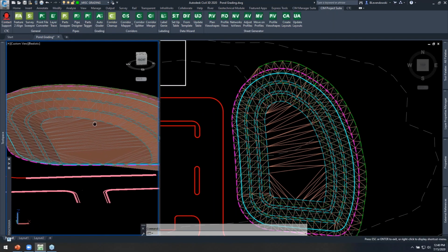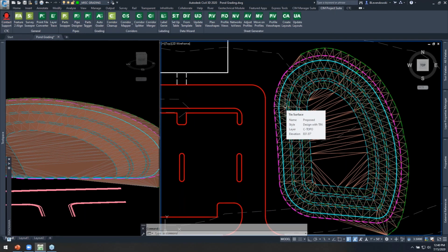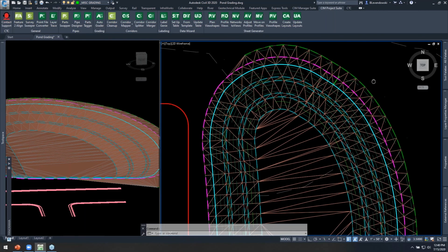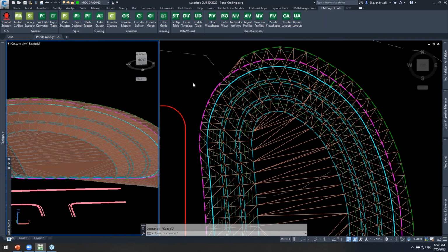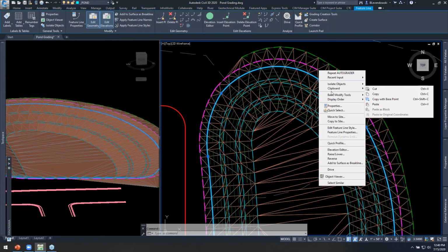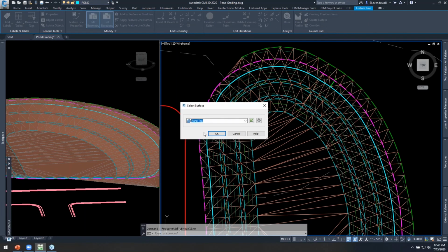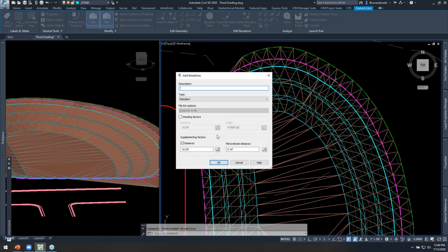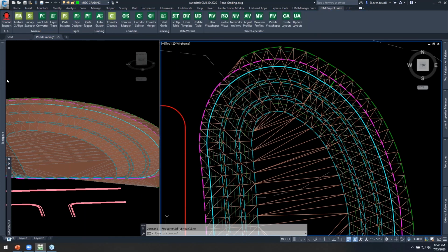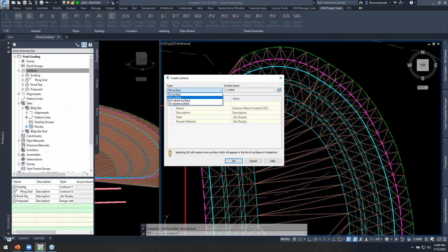What your pond design looks like, right, it varies, it depends. You guys have all different design standards, different preferences certainly. But from here, other things like your pond volumes, quite easy to do, right? Grab that, whatever that normal water line is. I'm going to use the parent feature line here. You just simply throw it into a different surface, okay? And then you just create a comparison. Okay, this is just native behavior here, a comparison between,